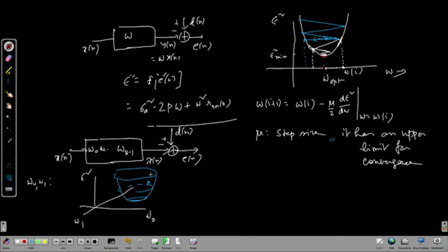So, I follow the gradient, and by that I am coming down and down in the vertical direction. So, that is why it is descent. In general, the philosophy is the same. I can extend it now to not just one filter coefficient but all the coefficients together. W0 I plus 1 is W0 I minus mu by 2 times the derivative with respect to W0, not others, and it will be a partial derivative now, del epsilon square del W0 at that point where overall W is Wi.